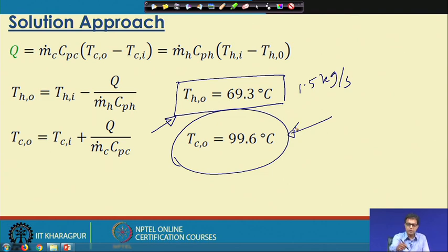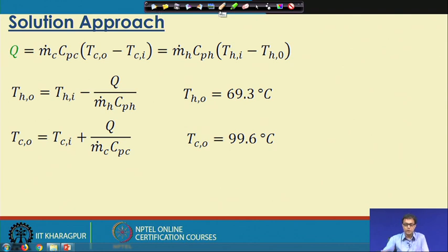Depending on the heat exchanger configuration, whether mixed or unmixed, and whether it is a simulation or a design problem, we have to take help of the F-LMTD or the LMTD, and look for the appropriate equation to solve for the correction factor F, or take help of the appropriate chart for calculating the correction factor, or the R or P parameters, and accordingly find the heat transfer or the design parameters. Thank you.